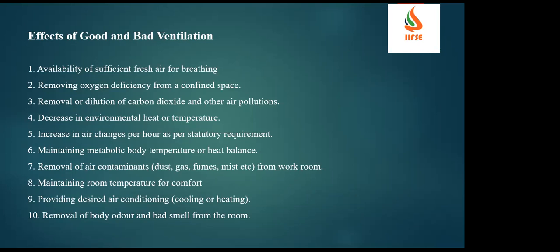If the oxygen percentage is more than 21%, that atmosphere is called oxygen enrichment. Oxygen enrichment is more dangerous for catching fire, and deficit will be a problem for people for breathing, suffocation, as the amount of oxygen will be less.